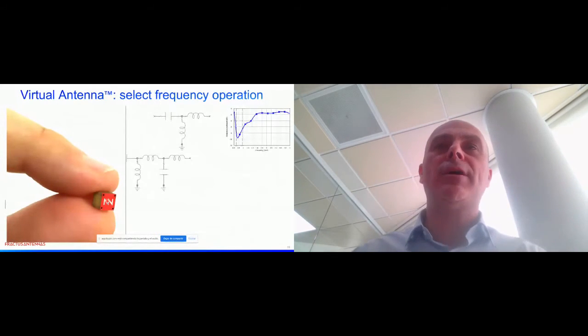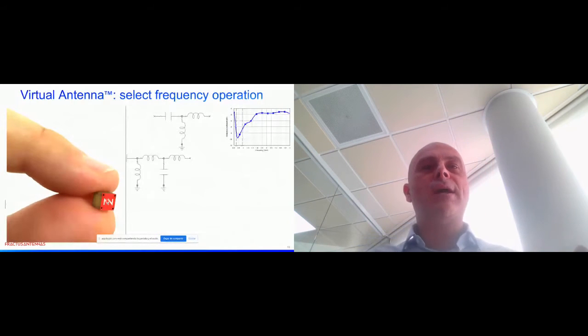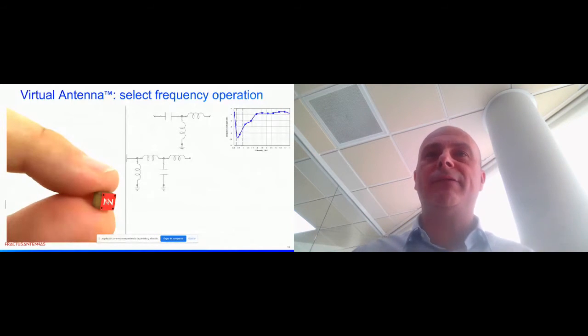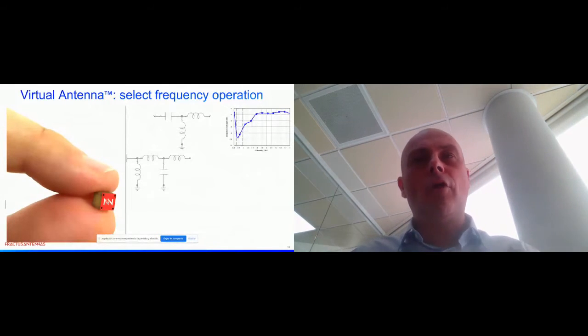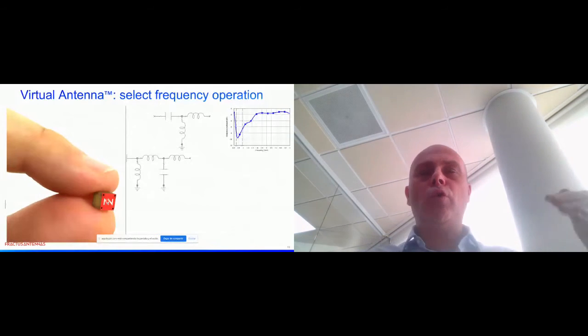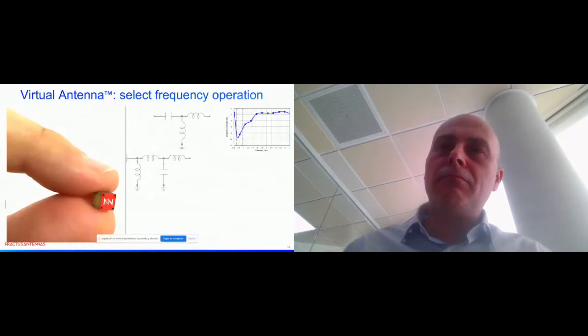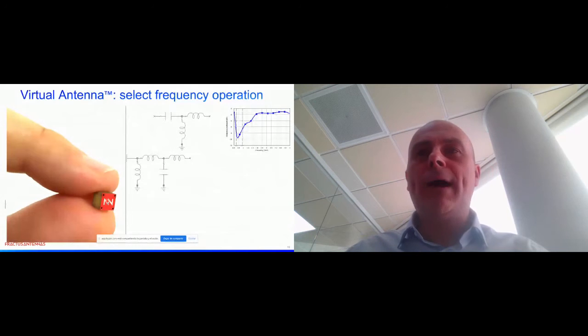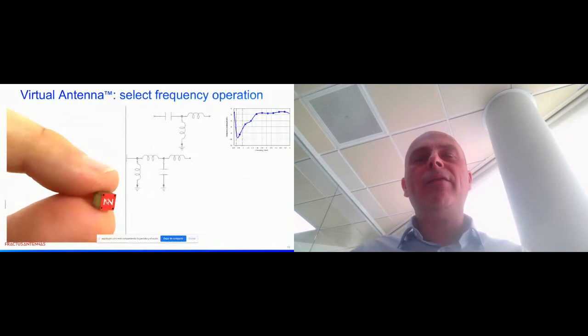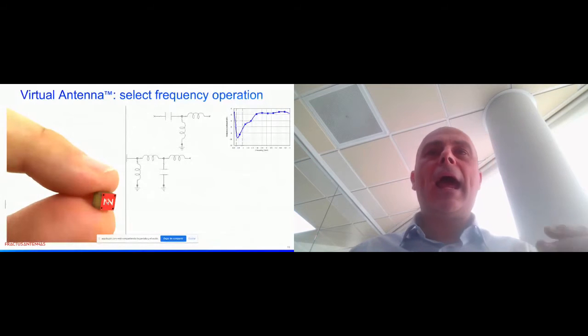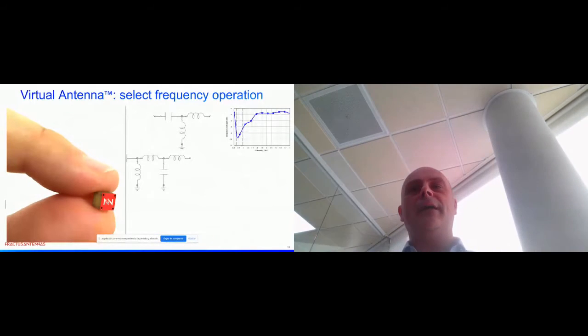In this case, if you use a simple matching network, which is a combination of very tiny passive components, capacitors and inductors, you can go from either a single band response at LoRa frequencies, perhaps you want to go beyond and include cellular IoT bands in a multi-band fashion, and also expand your bandwidth and include more bands. Everything can be easily done with a combination of antenna booster, of course, and with the addition of a matching network.